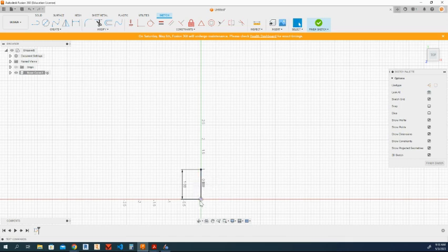Next, I'm going to come out from my shoulder. So I'm going to create a new line. It's going to come out this way. And what my shoulder diameter was, 1.283. Again, your numbers may change. But that would be the diameter, and I need the radius. So I'm going to divide that by 2. Let Fusion figure this out. Just get this number out of my way.